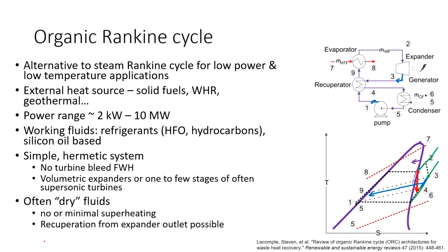And then, once the heat is transferred, up to the point of some minimum temperature difference between point 1 after the pump and the vapors, also a smaller part of the heat gets rejected in the condenser. So we save some heat from the heat input, and we have the lower heat rejection in the condenser.